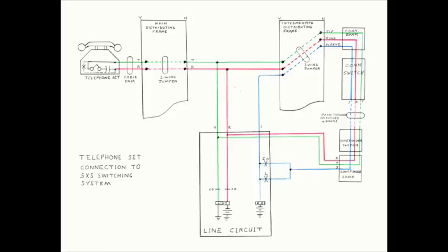The cables terminate on terminal strips or connecting blocks, which have a cable side and a cross-connection side. The cross-connection side allows interconnections between any two cable terminations to be made by installing loosely placed jumpers on the distributing frame.